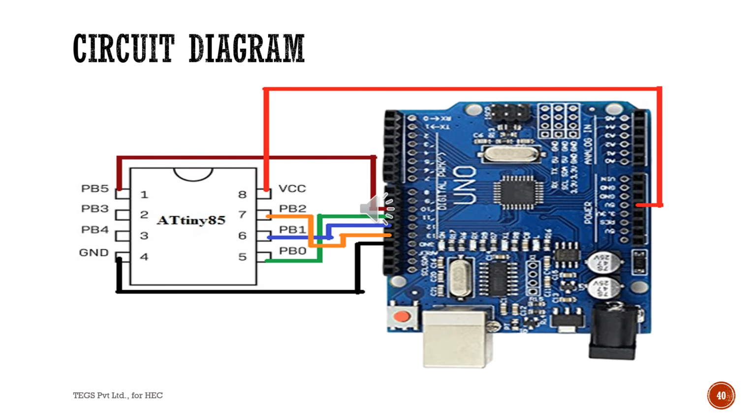Programming tool needed for the AVR family. This page shows the simple wiring of ATtiny with Arduino Uno. The Arduino Uno is flashed with the ISP program, and this transfers the program to the ATtiny through the master slave method. Remember to connect a capacitor in the circuit to program the ATtiny properly using this circuit.